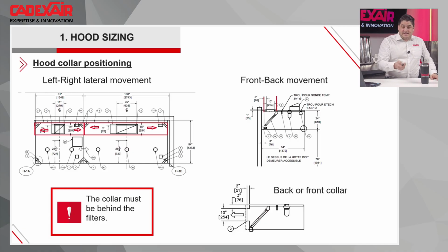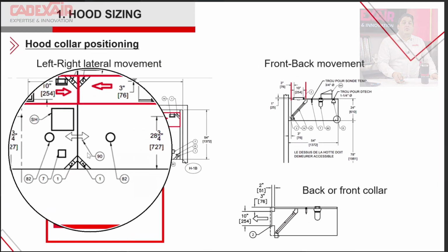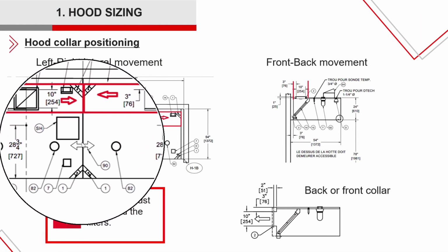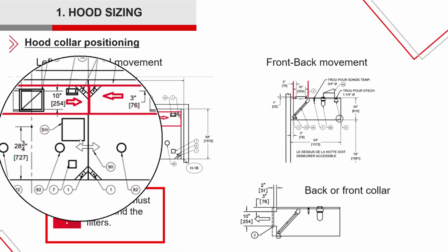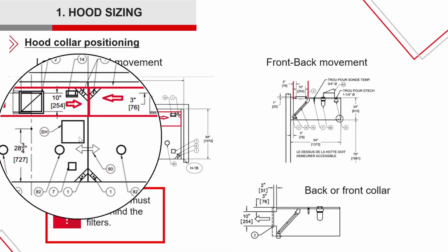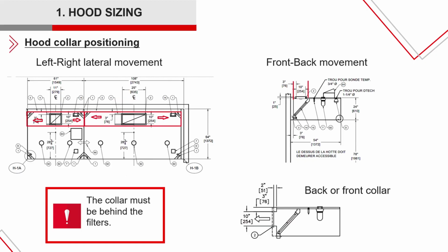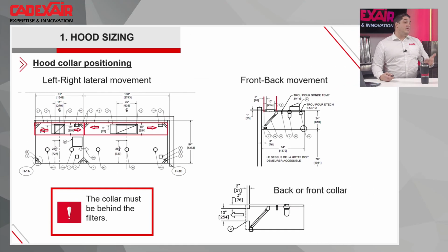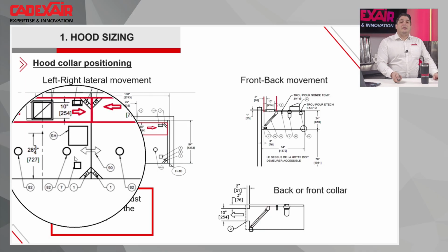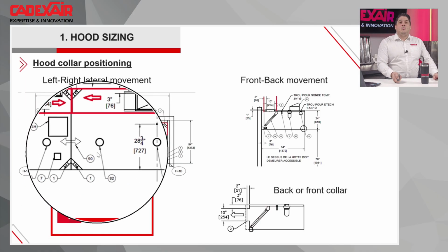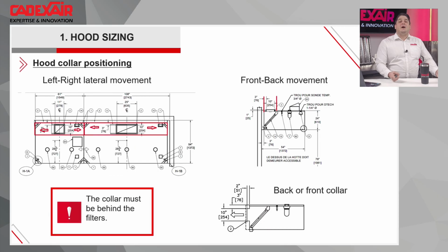And because I have this design right now, this is something I love doing. It's what we call an open plenum. So the front of the hood, the middle panel is almost all removed. The reason why: we did a project in a casino, an old project. They moved equipment around, and now they had a big kettle right somewhere at this spot, where the light is. So what happened, they opened the lid, there was a lot of vapor coming in, so the smoke started turning and was just stuck in the left panel of the hood.